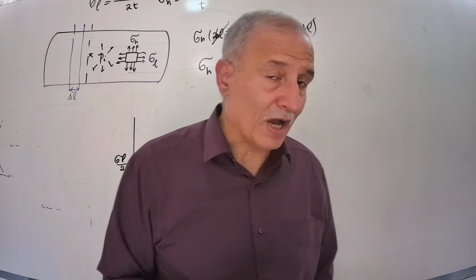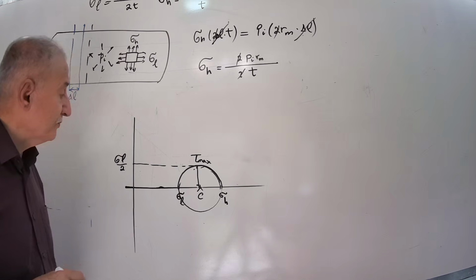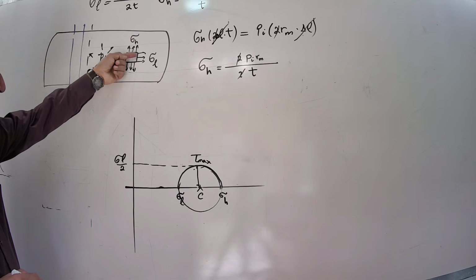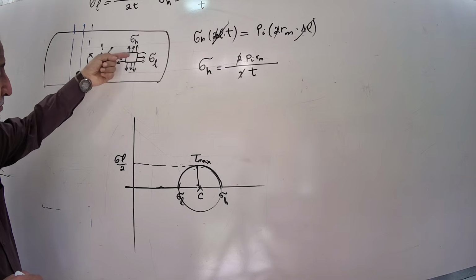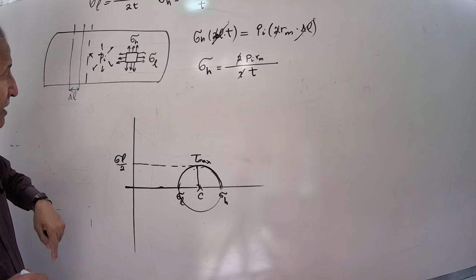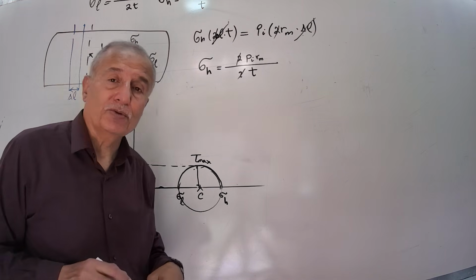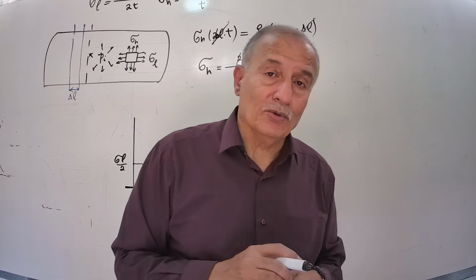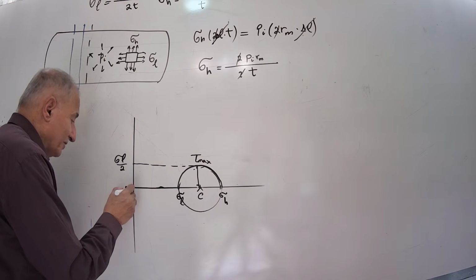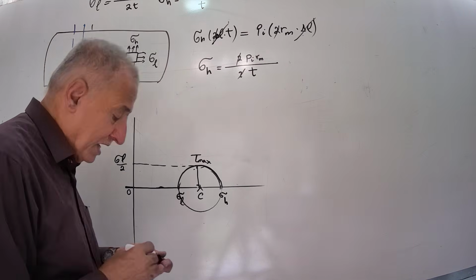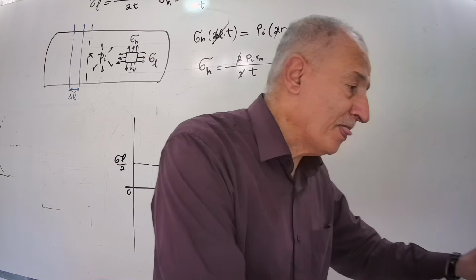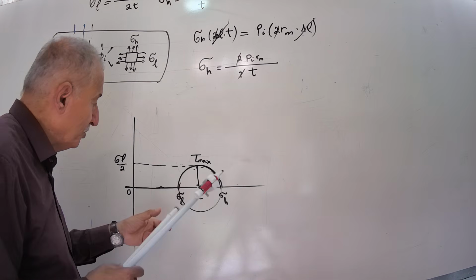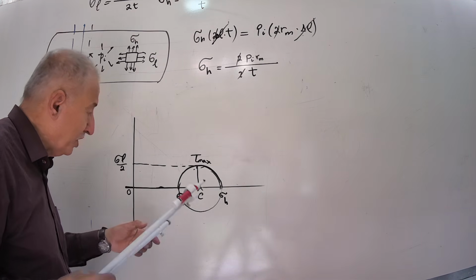No. Why? Because we have another stress, sigma z, that acts in the direction perpendicular to the shear, but the value, as I told you, is zero in this thin walled cylinder. Zero means we have only one stress here. And in this case, what happens? There is another Mohr circle between 0 and sigma h, and one between 0 and sigma L.